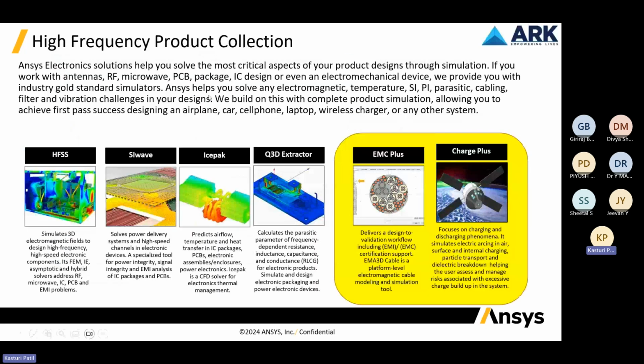These are high frequency tools, which include HFSS, SIwave, Icepak, Q3D Extractor, EMC Plus, and Charge Plus. In academics, HFSS is mainly used for antenna designing, metamaterial unit cell designing, filters and so on. SIwave is dedicated to PCBs, either single layer or multi-layer. We use it for signal integrity and power integrity analysis.